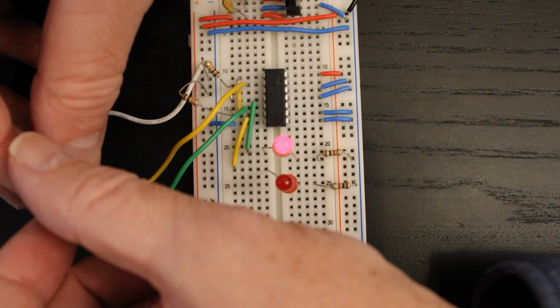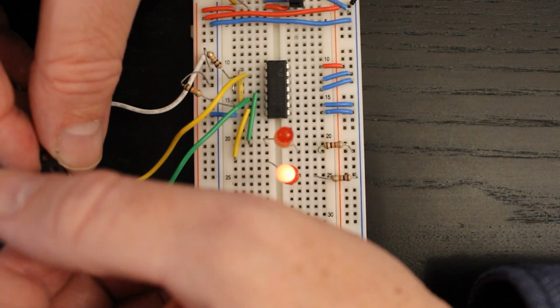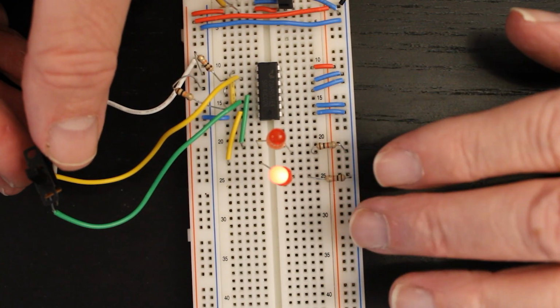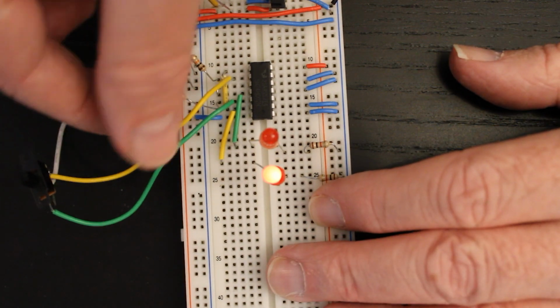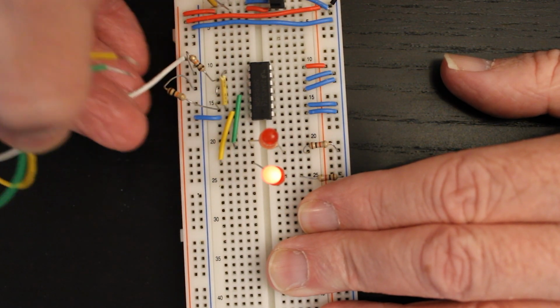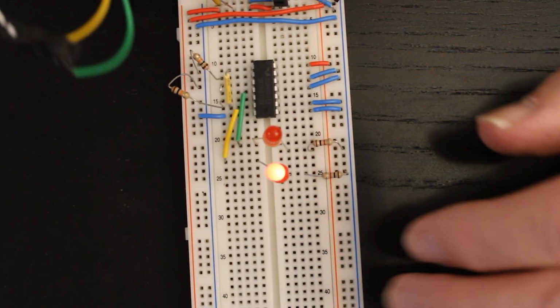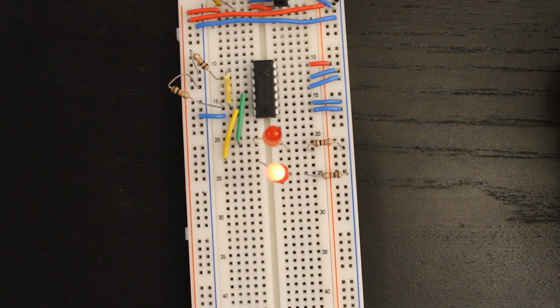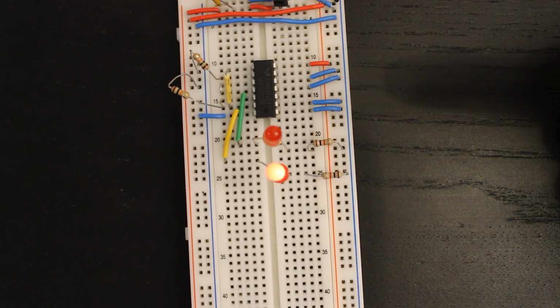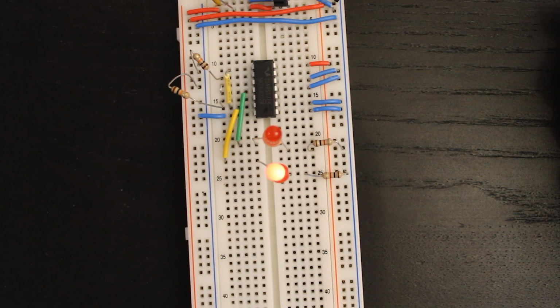And just to demonstrate that, if I now throw the switch back again, you see the state we're in now is with the lower LED lit and the upper LED unlit. And at this point, I can even completely disconnect the switch. And as you can see, the latch is holding that steady state. And that's really the functionality that it's providing us with that can be useful in debouncing a single pole double throw switch like this. I hope you found that interesting.